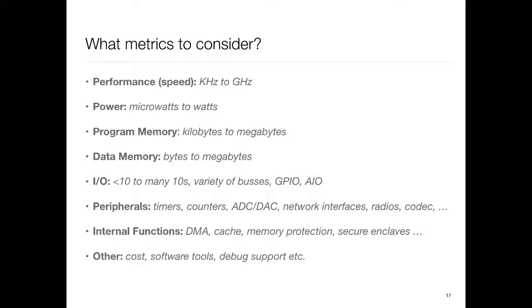Yeah, exactly. So basically you can almost think of it as there's a second processor whose task is to move stuff from devices to memory or memory to devices so the main CPU can go to sleep or do something else. Okay, so it's very commonly used to either save power or to increase performance. Caches I already referred to.